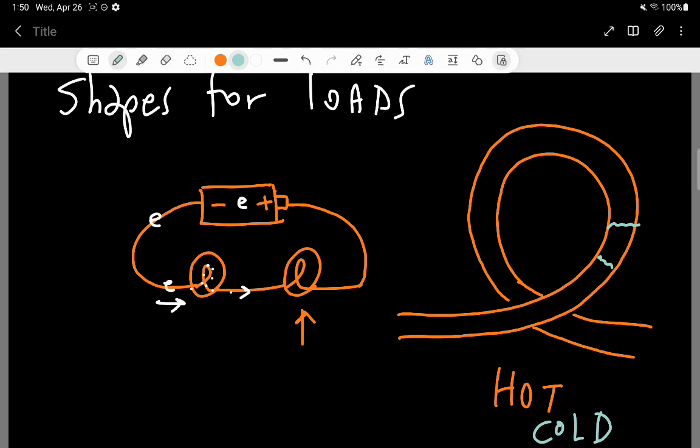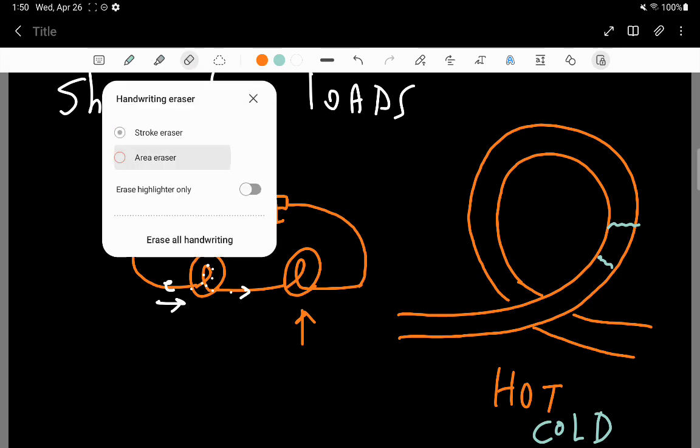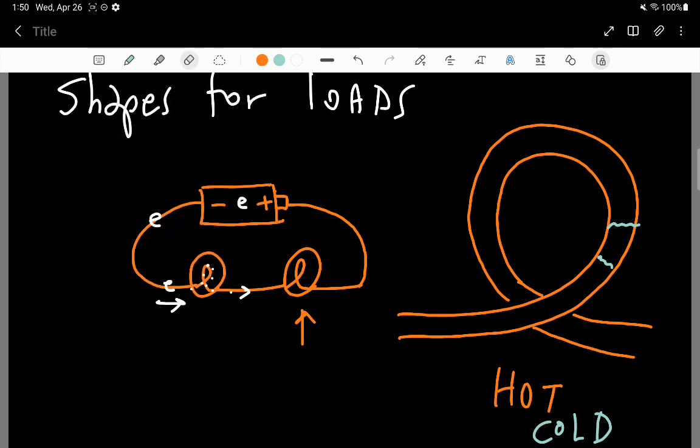And so let me see. So what I mean by that is in between here and here where it got really brittle, the wire actually breaks. So there are raw ends. So if I go and I draw that inside of here, so there's that little raw end, right? So this is an open circuit.